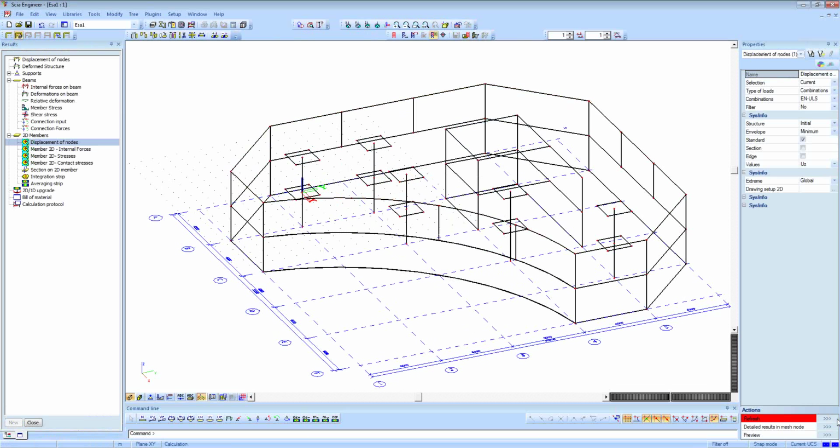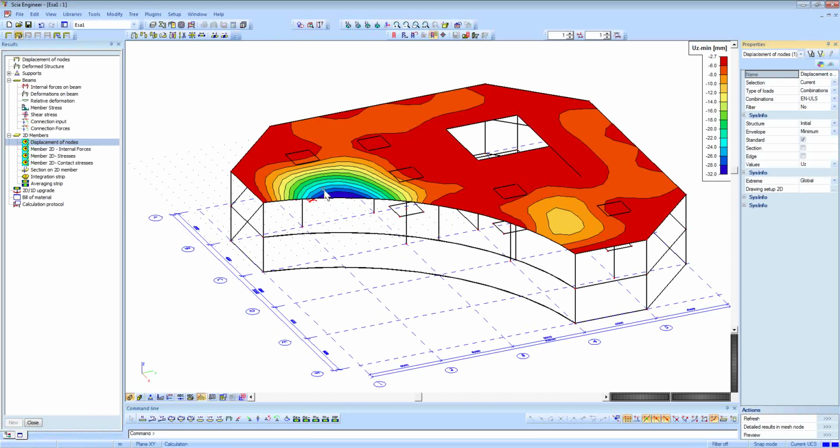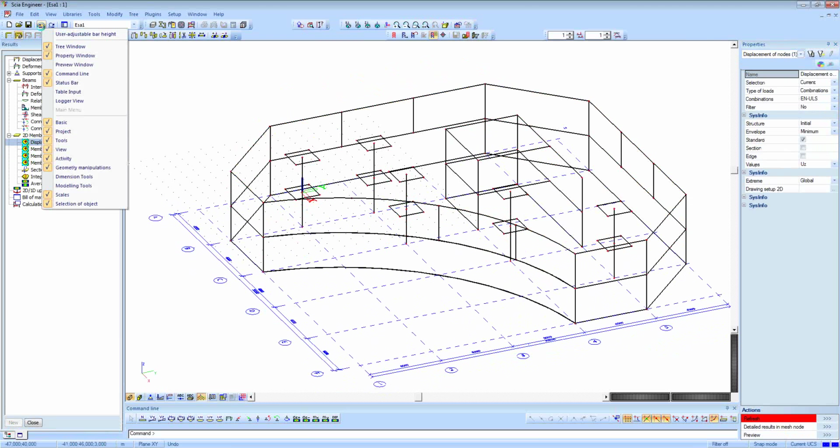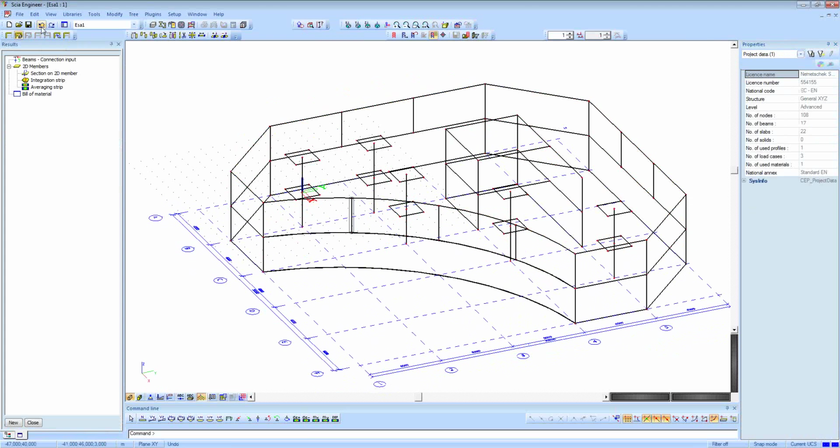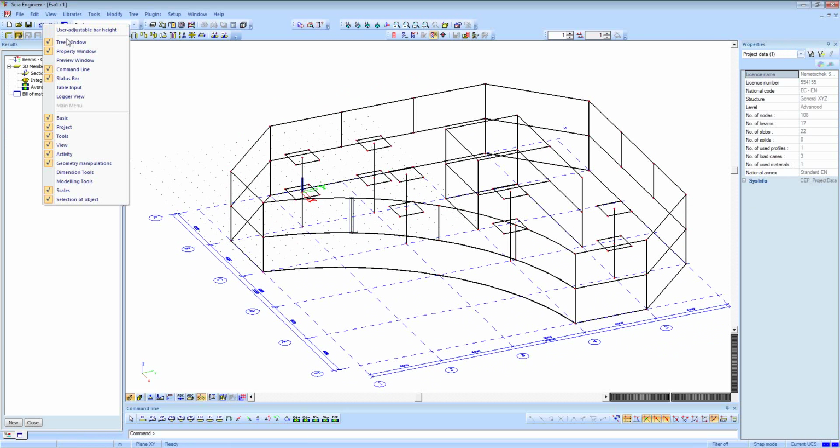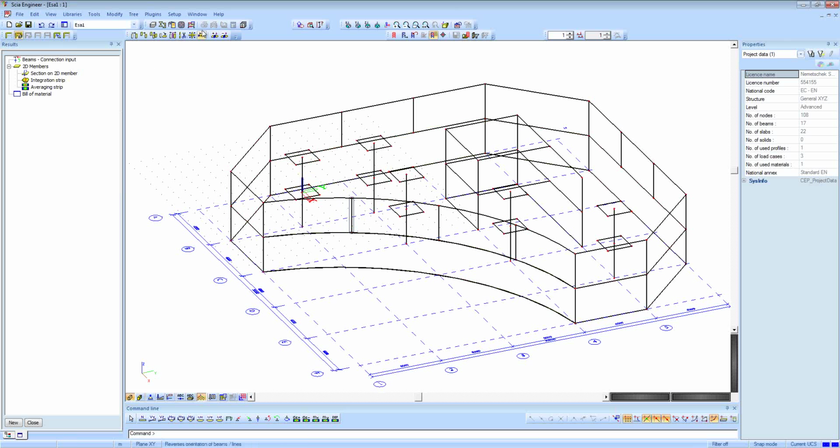Because the displacement becomes much bigger in the part where the column has been removed. And from 10.9 it has changed to 32 because the column has been removed. Now I'm going to use the undo option until the point that the column has returned. So, you can see it has returned. I have to calculate again, of course. So, you can see results in plates like that.